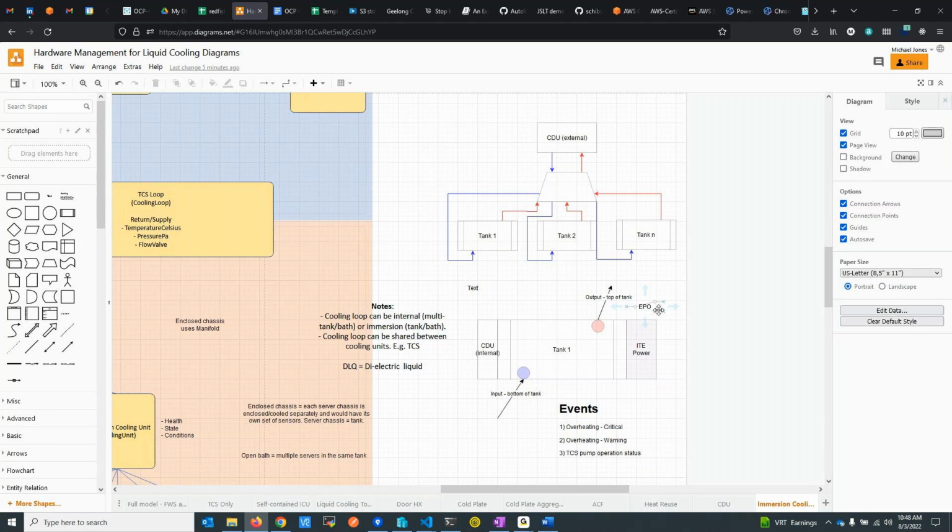Because we had the scenario with immersion cooling that it has to be able to cut the power going into the tank if there's any kind of overheating condition, because there are dielectric fluids that break down, etc., and all the rest of it. And I also think that boiling the glycol mix in a cold plate would be a really bad idea too. Yeah, Victor here from CoolIT was going to chime in.